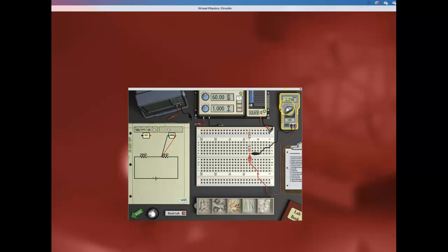And now here I need to change this into VDC. Okay, and then here I'm gonna get rid of this. This is the positive and this is the negative. Okay, then this is my reading for measurement. Now take a snip of the measurement for part A only, which is the voltage across R1. And then you are going to measure the voltage again across R2. The voltage across R1, we're going to call it VAB, and the voltage across R2, we are going to call it VBC.